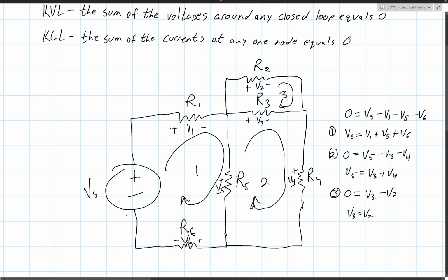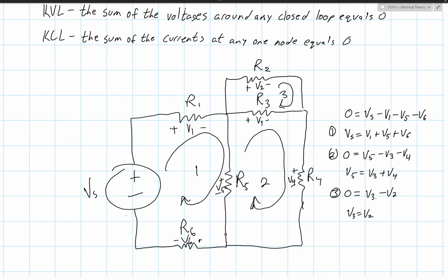If you're a physics major and you're coming in this way, that's going to be a voltage rise. If you're coming in this way, that's going to be a voltage drop. It doesn't really matter. You still get the same answer. Technically, just pluses and minuses are backwards, so it's not a big deal. Just be aware if you go into a physics class, they might tell you differently. But it's okay. So that's the KVL.